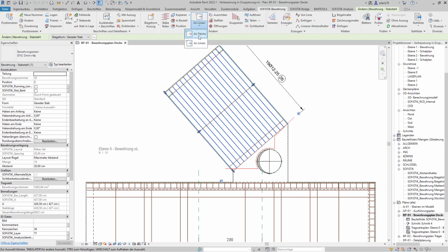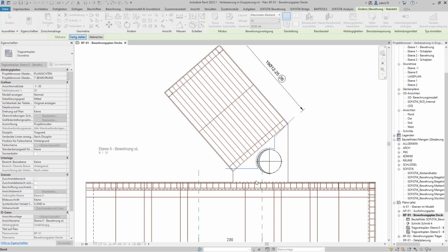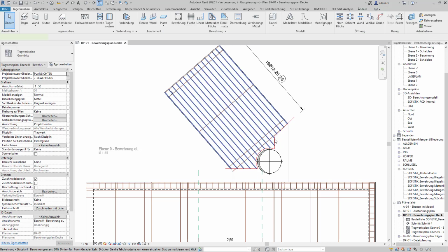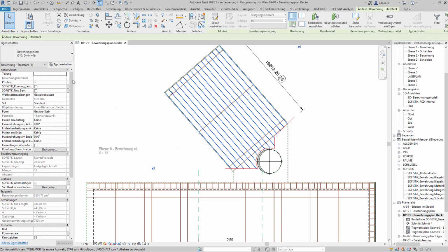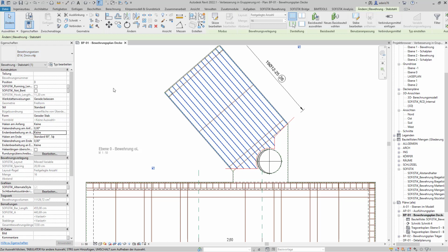Using the example of stretch trim two lines, we can see that with version 22, a reinforcement container is no longer created in Revit, but a standard element consisting of freeform rebars. This means that you are no longer so restricted in any post-processing. You can add hooks to those elements at any time or change the diameter, for instance, which was not possible with the old rebar container.